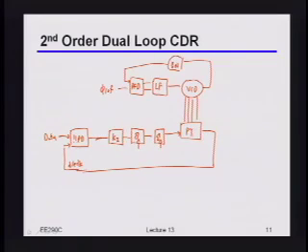Yeah, I have a feed-forward path, and in particular, where does that get added in? From the output of the first accumulator. Yeah, exactly. So by direct analogy with a normal PLL, I'll have something that's usually called the proportional gain, and I'll have that jump around the integral section, and then feed that proportional gain into the last accumulator. Okay?